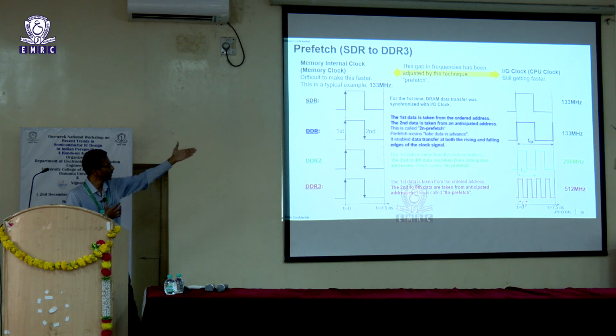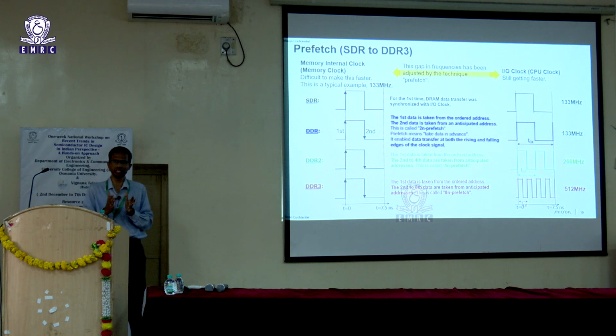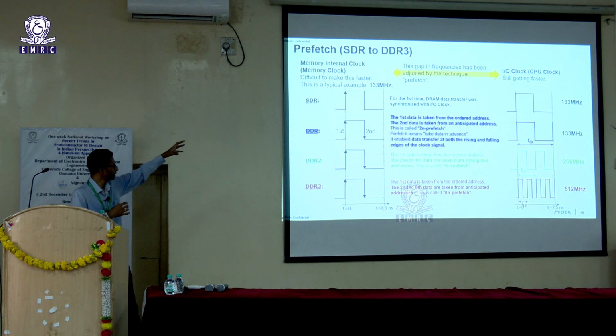So we have been seeing significant growth in the processor regime, but the access time of memory is typically staying constant because of the kind of dimensions that we are working with. So even though there is no change here, we are somehow, generation on generation, improving on these access rates, speed. So this is how we do it. We started off with SDR and then we go to DDR. So in DDR we take both the edges here and have data captured at both the edges.